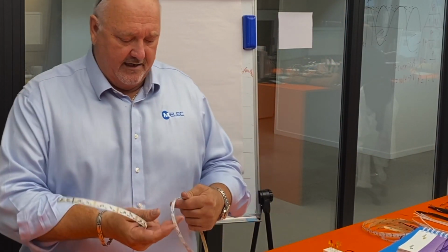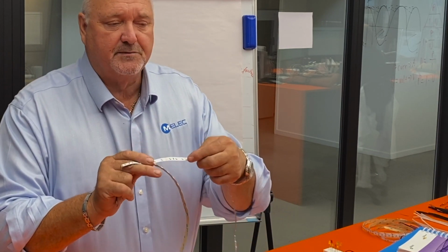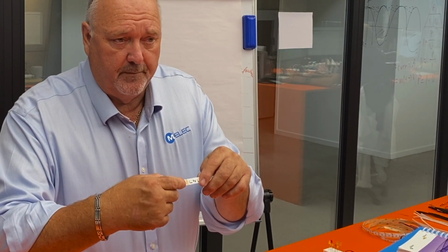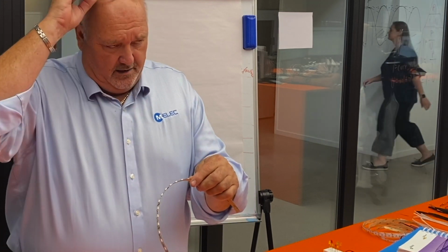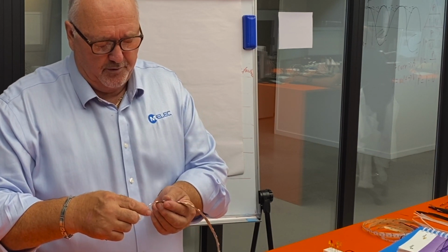Now, if you look at the LED strip here, you can see you've got two copper dots. That tells me straight away that's a single colour. When you look here, and it might be a little bit hard with the camera, you can see it's got multiple copper dots. That tells me straight away, if I was to put my glasses on, I can see that I have got RGB, W and WW. So that tells me that I've got red, green, blue, white and warm white, and the combination of the white and the warm white will give me neutral white.